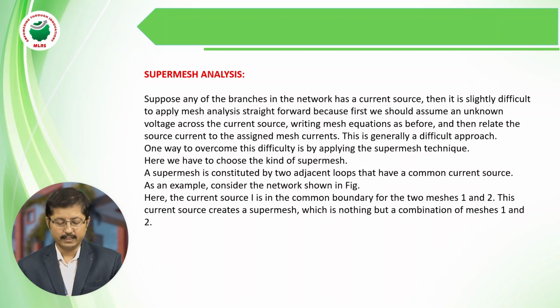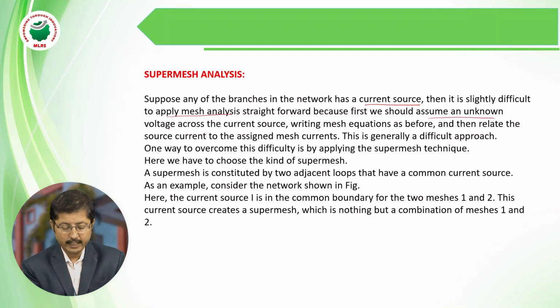So now we are going to discuss super mesh analysis. Suppose any branch in the network has a current source, then it is slightly difficult to apply mesh analysis straightforwardly, because first we should assume an unknown voltage across the current source, write the mesh equations as before, and then relate the source current to the mesh currents.